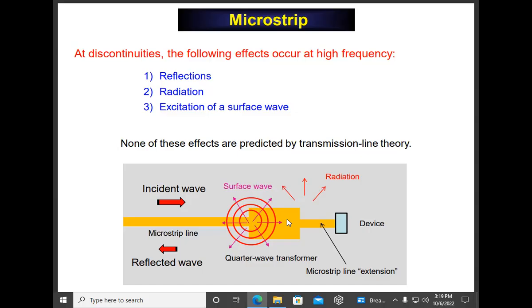Okay. Now remember, what we do worry about for a lossy transmission line is the attenuation in dB per meter. That's what we care about. We don't care about the fact that the Z0 is changed by 0.01% or something like that. Does that make sense? Okay.